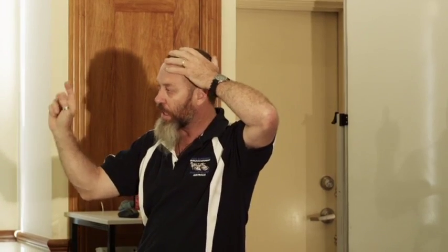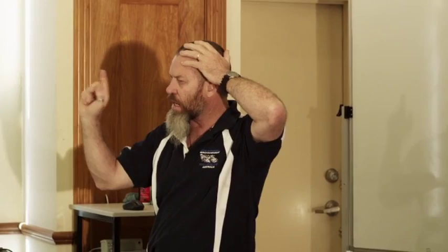Wind region C is the 50 kilometres right on the coast, and I think it starts up at Bundaberg and runs right around the top, right around to Darwin, and right down the back, I'm not sure, somewhere further down south. And then there's wind region D, which is over in the Carnarvon area in Western Australia. And it's the highest risk because it's about cyclones.